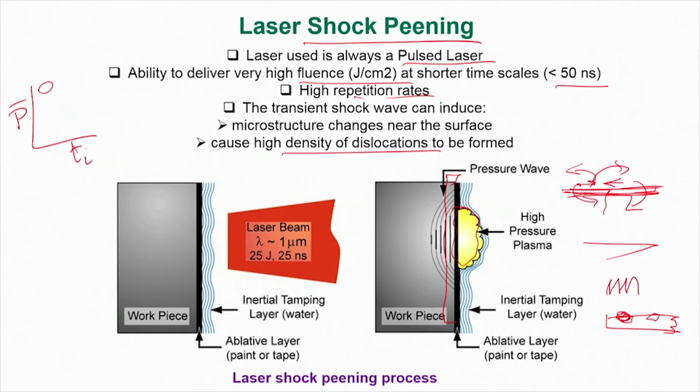So here also you can affect only this very precise corner of the cutting device, or the shear component, or some sharp edges, or maybe the curved portion of the acetabular cup can be given this kind of a treatment to create residual compressive stress. And you can do that very precisely, exactly where you want, and avoid heating other zones where you don't want.